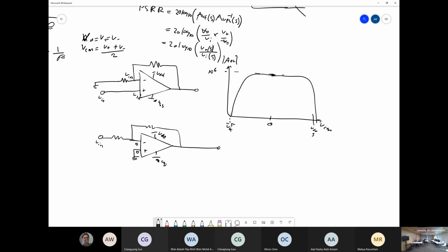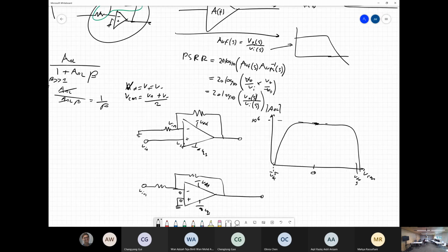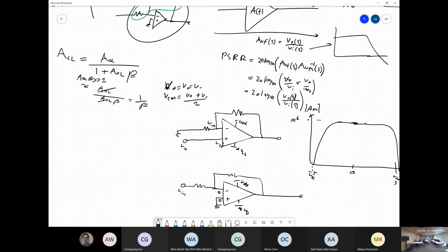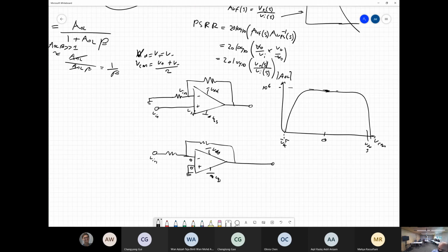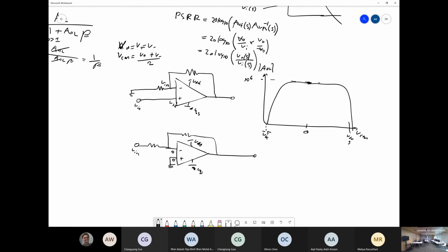When the voltage gets too close to the rails, as you saw in the labs, the op-amp starts to turn off, right? It can't swing all the way to the positive. It can't swing all the way to the negative. It's because the op-amp turns off. When the op-amp starts to turn off, you lose open loop gain. And when you start losing open loop gain, remember I made this assumption where the value is really big. It's no longer really big. The op-amp stops. You lose accuracy, right? So, tricky question there.